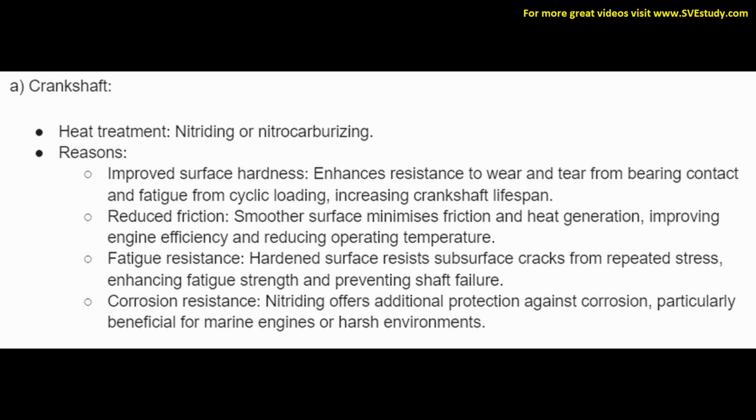Fatigue resistance. The hardened surface resists subsurface cracks from repeated stress, enhancing fatigue strength and preventing shaft failure. Corrosion resistance. Nitriding offers additional protection against corrosion, particularly beneficial for marine engines or harsh environments.